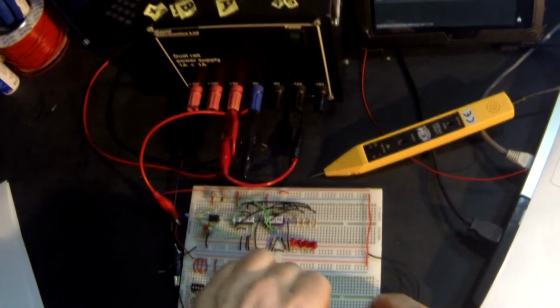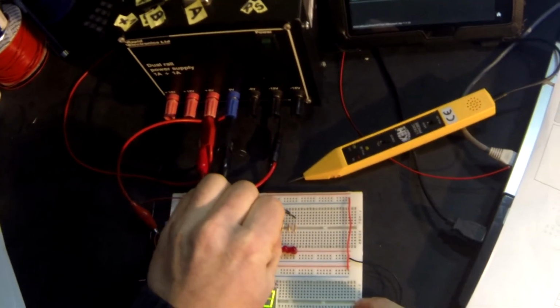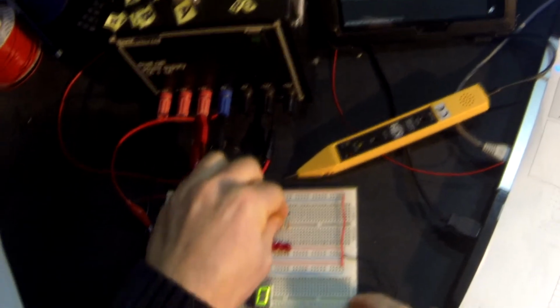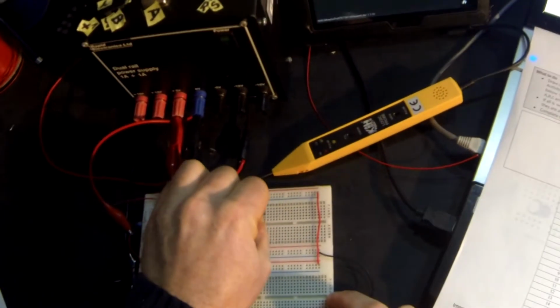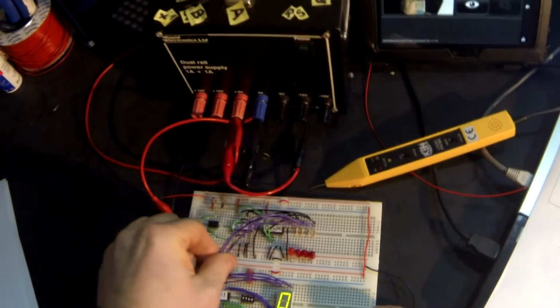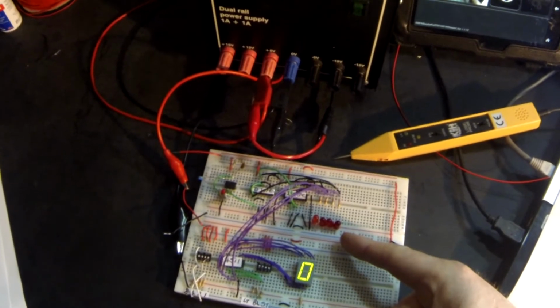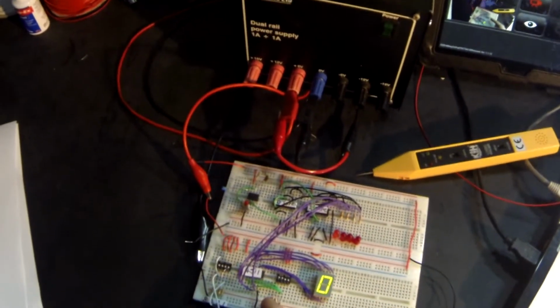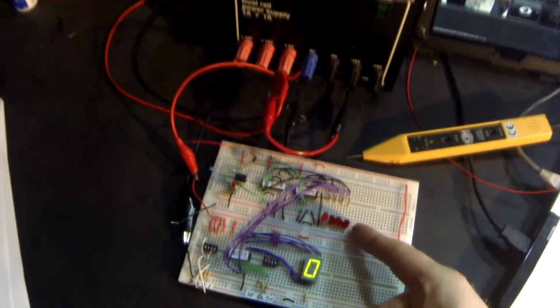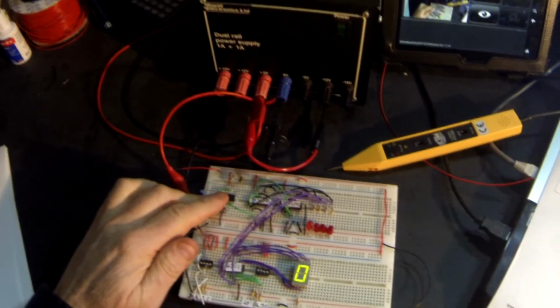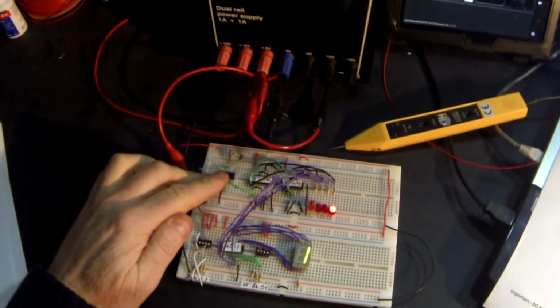Now I'm connecting them in and I'm leaving the LEDs in the circuit at the moment. I'm hoping that this will work. Sometimes it doesn't because the LEDs interfere with the signal, because of course we have a voltage drop across the LEDs. So because this is a digital circuit and the voltage will have dropped here because of the LEDs, it might mean that the logic signal is not right, but we'll look at that if that happens. So here we go. Good, seems to be working.